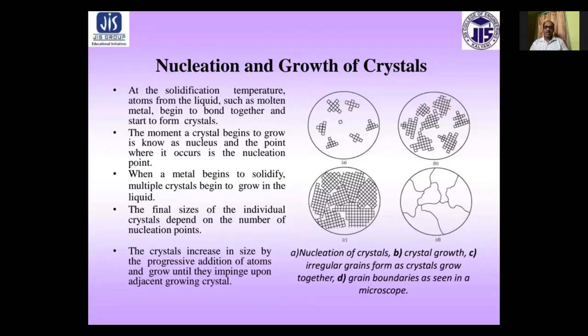The critical size is greatest near the melting point, but the probability of forming such a large nucleus is less. Particles smaller than the critical size will be dissolved by the vigorous bombardment of neighboring atoms and cannot grow gradually. These are called embryos.